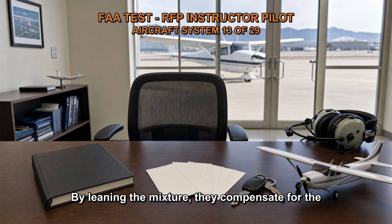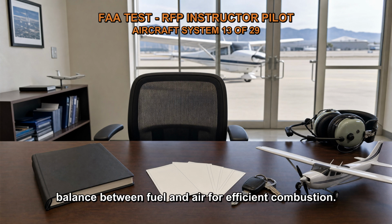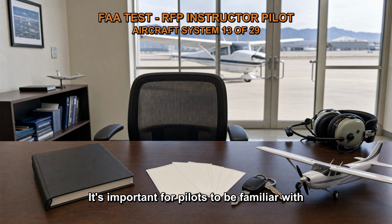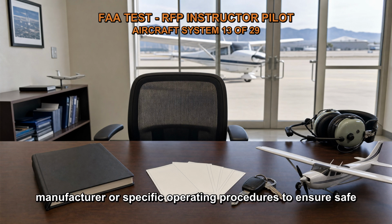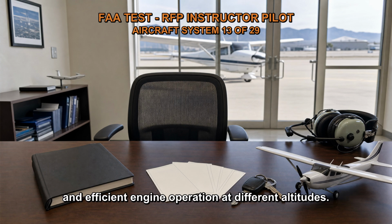By leaning the mixture, they compensate for the decrease in air density and ensure the correct balance between fuel and air for efficient combustion. It's important for pilots to be familiar with the proper leaning techniques recommended by the aircraft manufacturer or specific operating procedures to ensure safe and efficient engine operation at different altitudes.